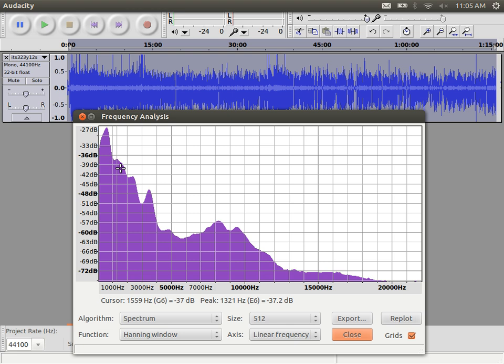In this case, let's say if the signal strength is below minus 57 dB, this line, we will ignore that. Or maybe 54, this line. That is, say all these values are 0. Then we would say the bandwidth of the audio ranges from 0 up to this point, which is about 4,000 hertz.